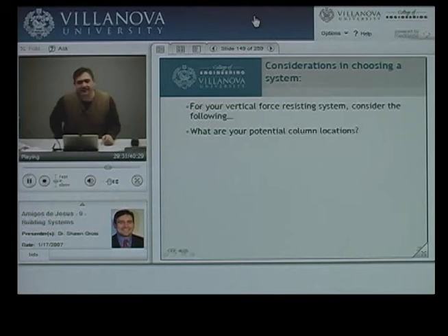So what do I need? I need some large-scale horizontal beams or girders to transfer the load out to the existing column locations. If I need to add columns, that's another common situation where you wind up dealing with architects a lot, which is the need to add or increase the sizes of columns in terms of what they suggested on your particular structure.